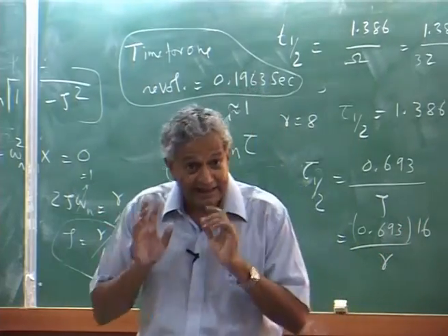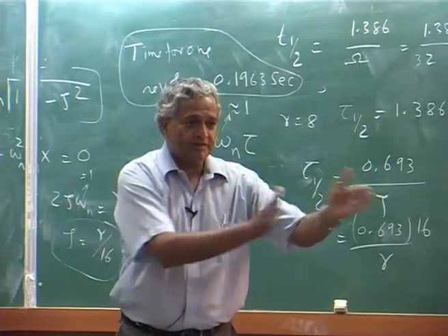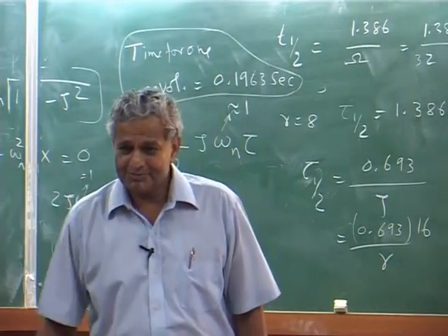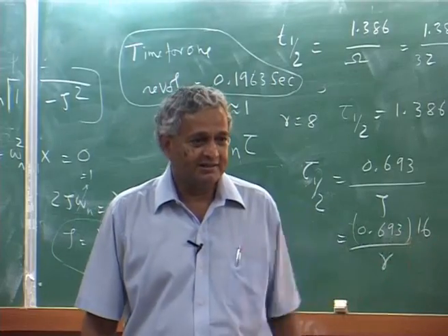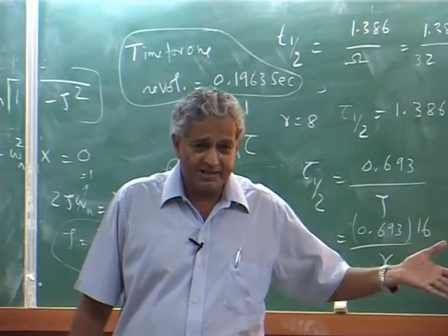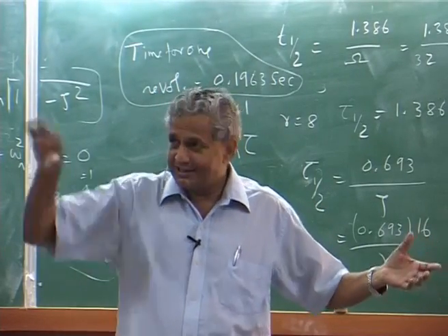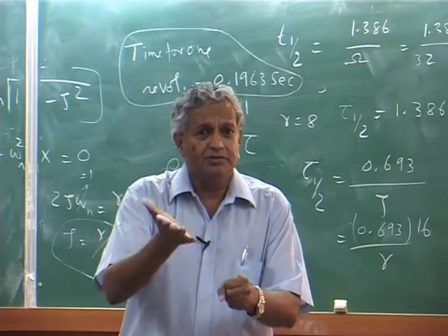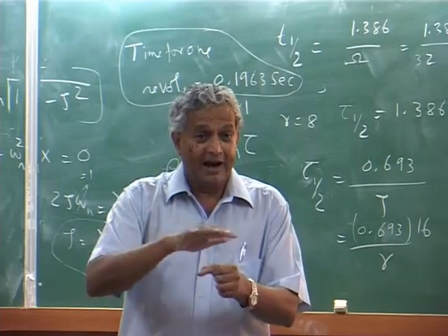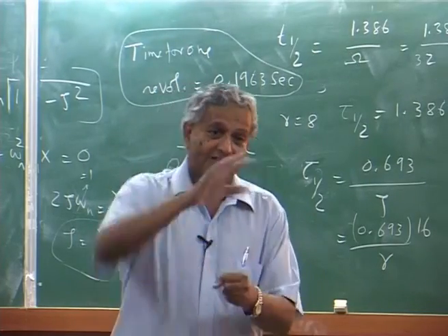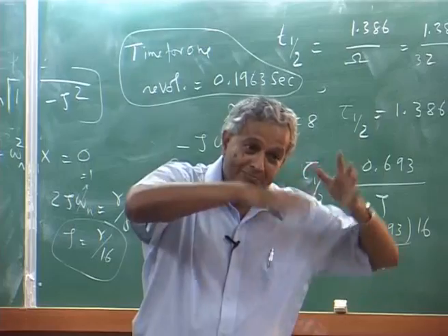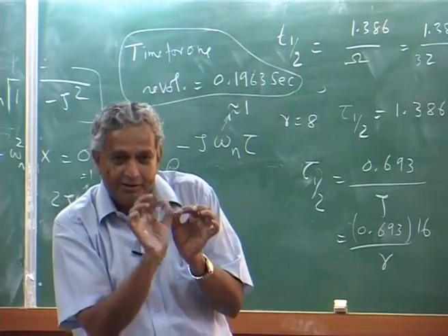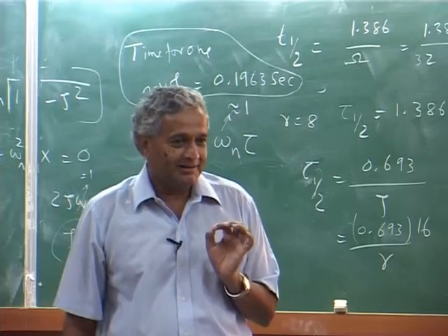That means the flap dynamics I neglect, I look at the steady state value. I give this input, I neglect the dynamics, only steady state. The moment I look at the steady state value, the dynamics is gone. Give input, there is a change in force, that is all. How the change in force has happened is because of dynamics of flap motion, the change is happening over a time, but I neglect that.